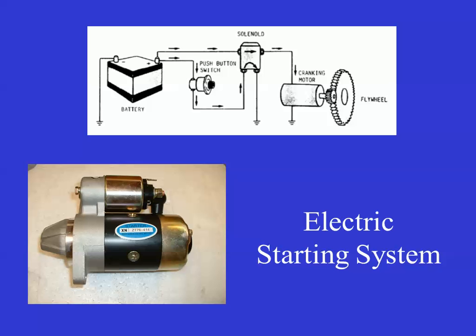Electric starting. Electric starting is popular with small engines. One of the things I want you to realize, though, is the amount of current involved. When you're talking about electric starting, even on a big block V8, you're talking hundreds of amps on start. Look at the cable that is going from the battery to the starter. It's very large. That's because there's a lot of current.